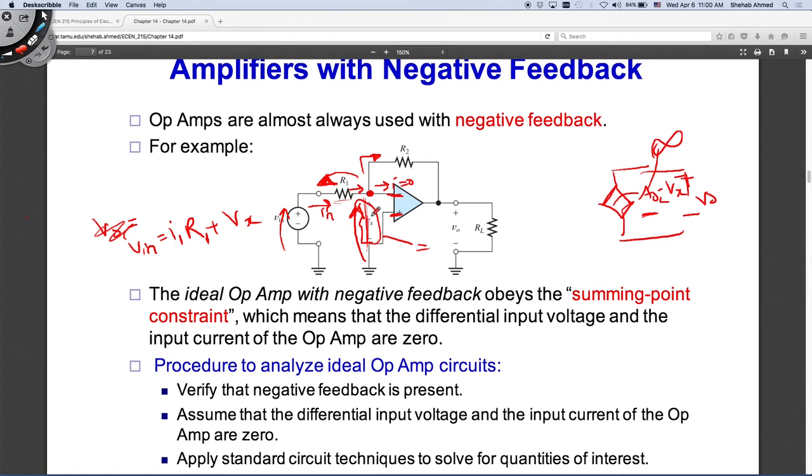So if I drive this to 0, then it's an open circuit, but it has a voltage across it of 0. So I can do a Kirchhoff voltage law around this loop, and this equation will be correct. And this just will happen to be 0, which means that the input current is equal to V input divided by R1 in this case. What does this current equal? This current here is equal to this current as well, because this current is equal to 0.